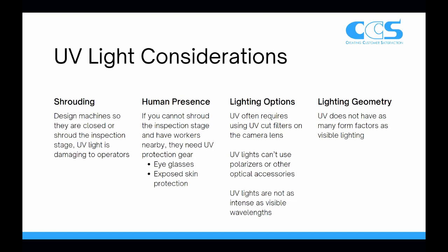And then another thing is UV lights are not going to be as intense as the visible wavelengths. The LEDs themselves are just not as powerful. And then if you factor in the camera spectral response, it might take 2 to 4 more lights than a standard wavelength would give you to get the same results.